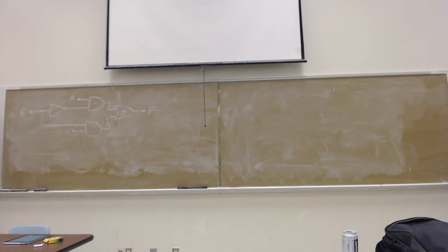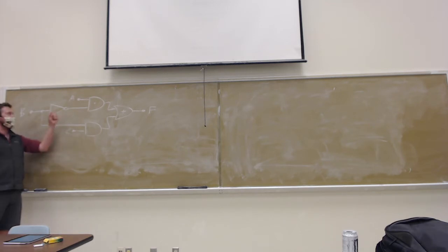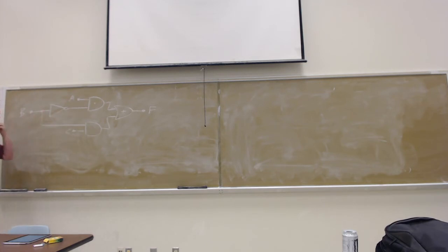So this is a two-level AND/OR circuit. Don't forget it's two-level because, for the purposes of quantifying everything, we ignore the presence of the inverter, although here it's going to lead to some interesting results. So this is a working logic circuit. It's got a whole truth table. We're going to focus on one specific set of minterms, the transition from 1, 1, 1 to 1, 0. We're going to drill down on that.